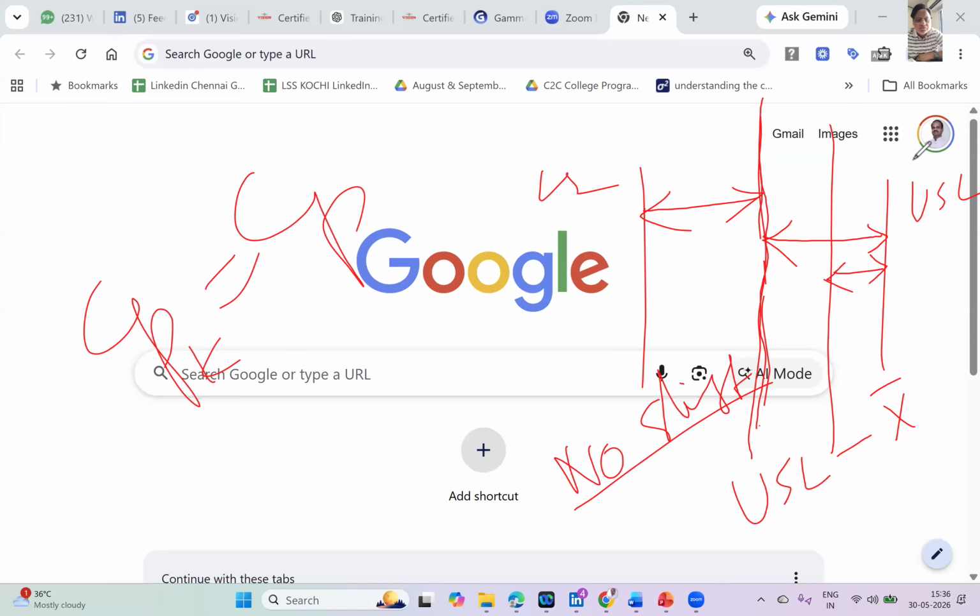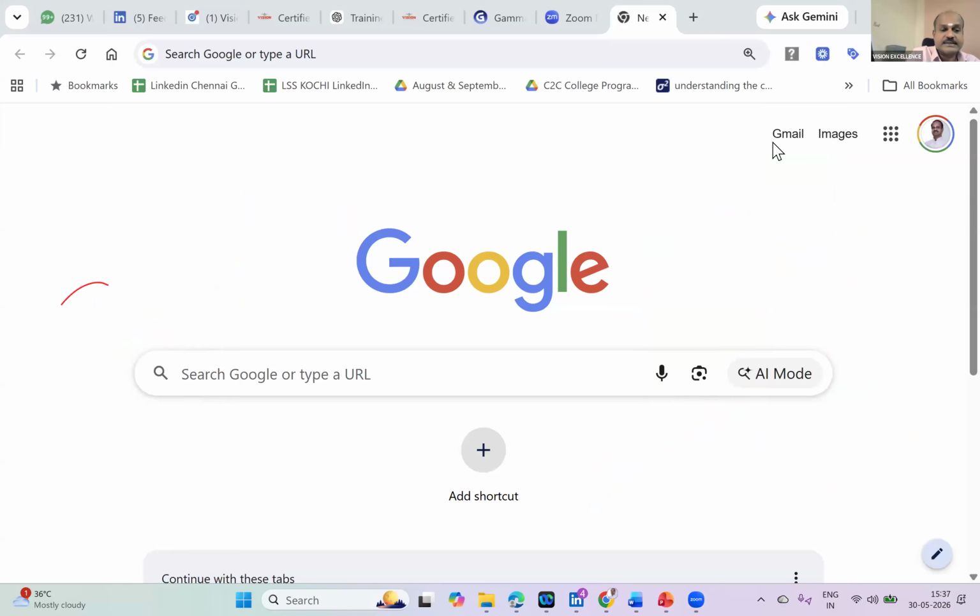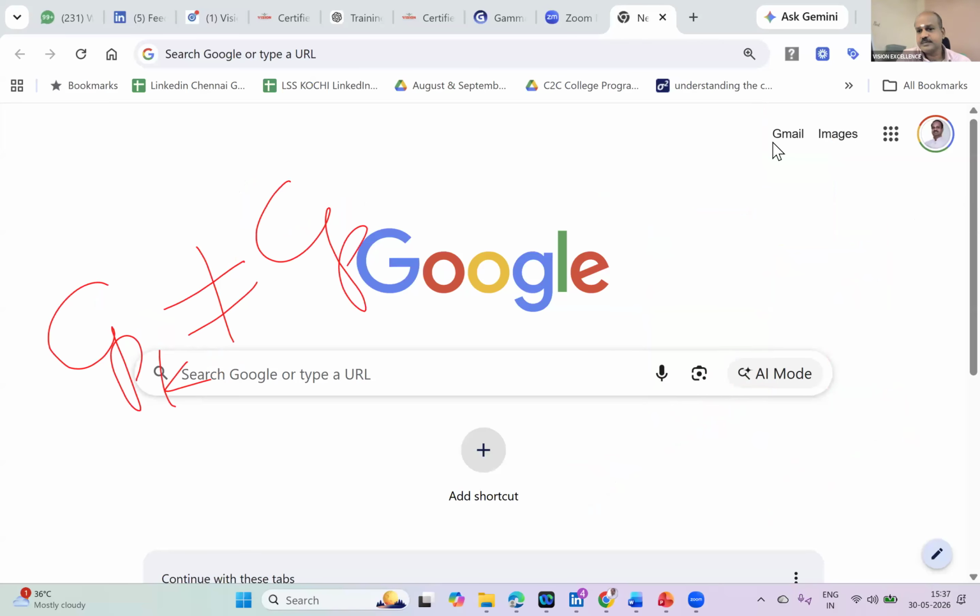If the driver is doing his job perfectly, you don't have to doubt him further. He is driving at the center, then whatever you expected with the CP, the same will be the value for CPK. But if the process undergoes a shift, then in such a case, CPK will be different from CP. Do you understand? Then only you should calculate CPK. Otherwise, no need to calculate CPK. How to calculate CPK? I'll tell you.